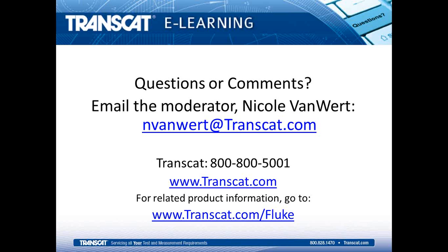Yeah, that's a great question. It doesn't necessarily need to come back to the manufacturer unless we feel like there might be something up with it. So we do want to make sure that it's stable. The reference probe, you'd want to look at that at temperature and make sure that it's not drifting around and it seems to be meeting the specification the manufacturer put on stability. But when you're not considering what the temperature display of the dry well says, and you're relying on a reference probe, there really isn't a need to send that in routinely unless you think there's a problem.